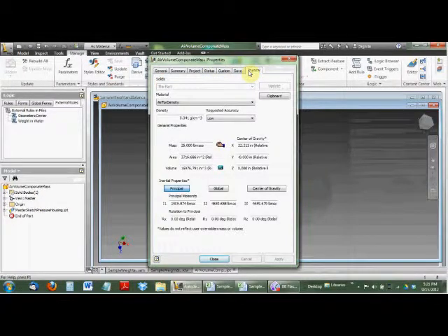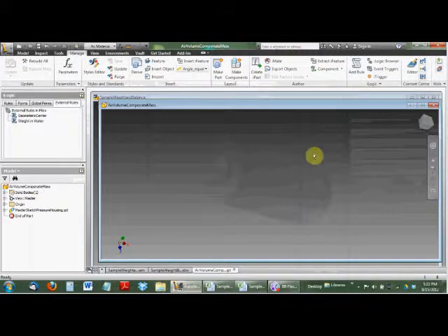So basically, I gave this air volume, which has some very small amount of mass, I wrote in 25 pounds because I'm pretending that I have 25 pounds of internal components, okay? And I just wrote that in. You see this little hand here instead of a calculator. This hand means that I have fudged that value. I've manually put in a value. And so that's a way to simplify your models, but still get all the data that you require in terms of displacement and mass and so forth and so on. So that's what I've done there.